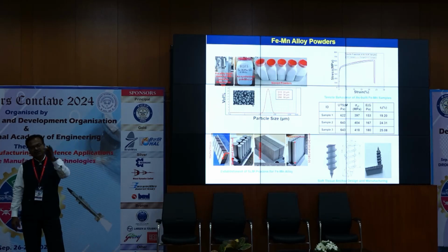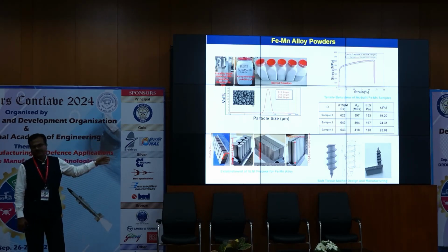And the coarse ones can be fed into our E-beam, electron beam melting, because they need plus 70 microns to minus 150 microns. And the remaining final powders can be used for coatings, cold spray coatings.